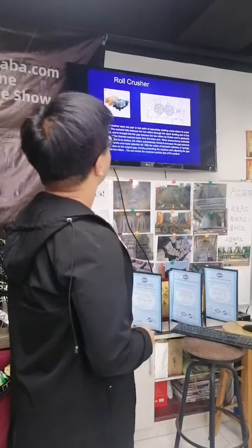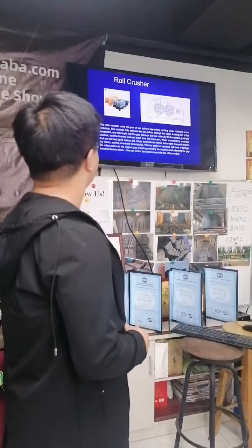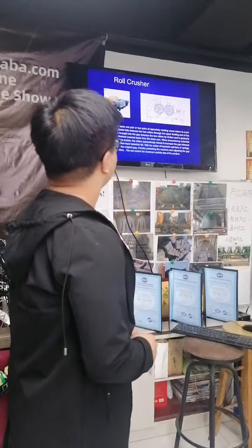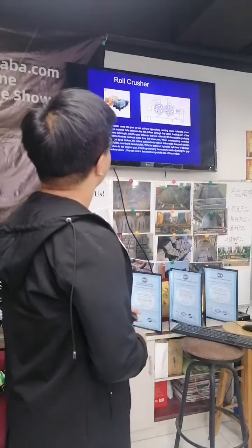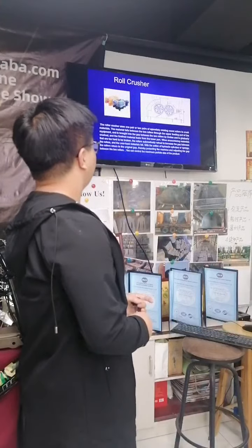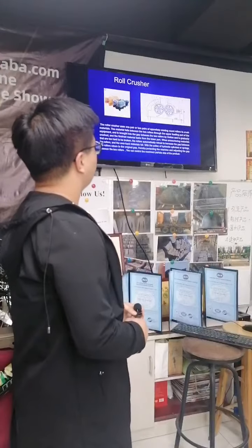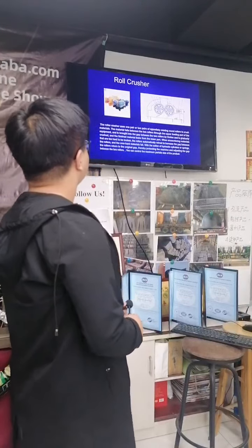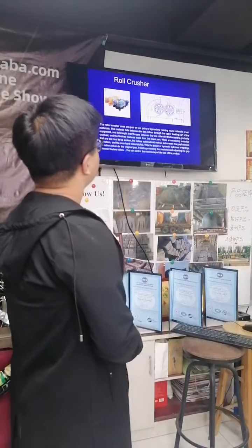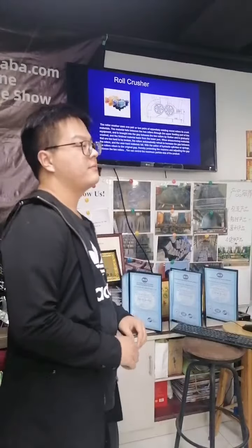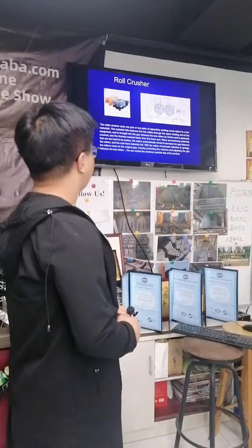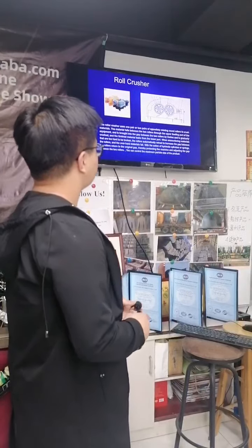When encountering materials that are too hard to be broken, the rolls retract to increase the gap between the rolls and the overhard materials fall. With the action of hydraulic cylinders or springs, the rolls return to the original gap, thereby protecting the machine. By adjusting the gap between the two rolls, we can control the particle size of the product.